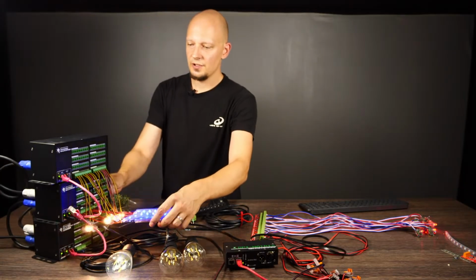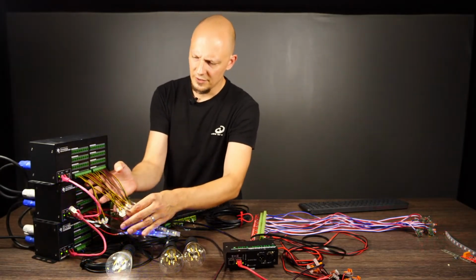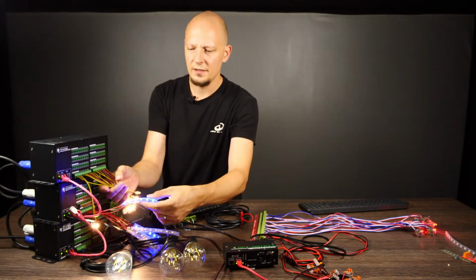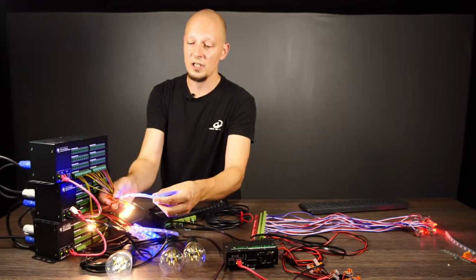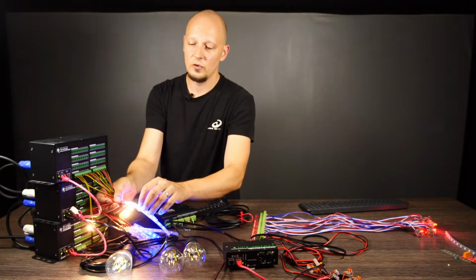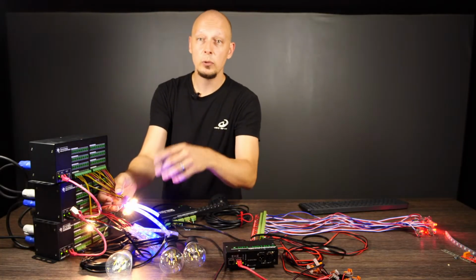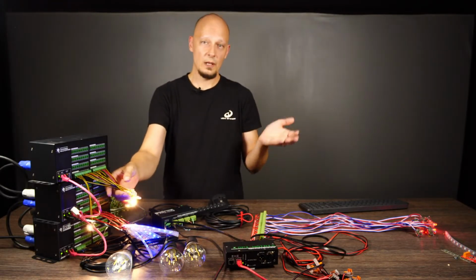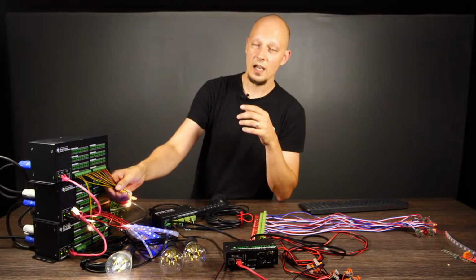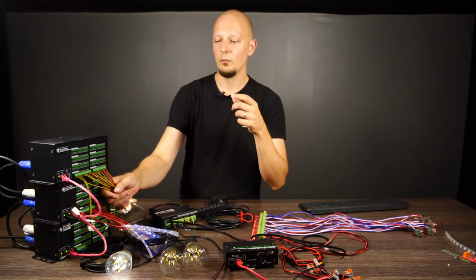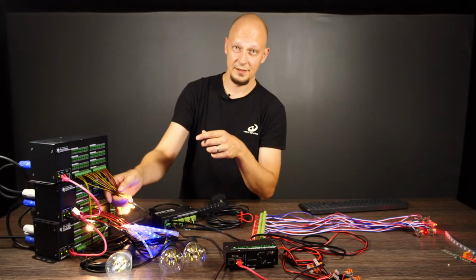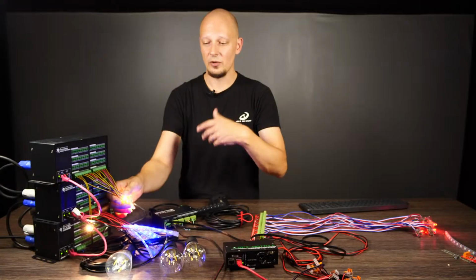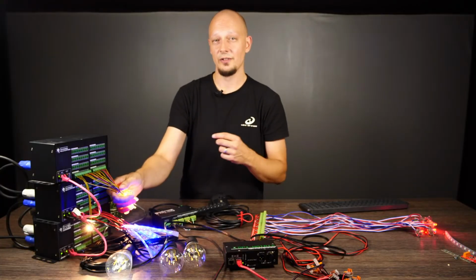So these two versions, I think these are 24 volt pixels, yes, and these are standard 12 volt RGB pixels. And the reason you can now see the blue LEDs on is that I have only connected the plus, and to the other channel I have connected the blue pad on the LED pixels. If I would connect the green pad, I would only light up the green color on the RGB pixels.